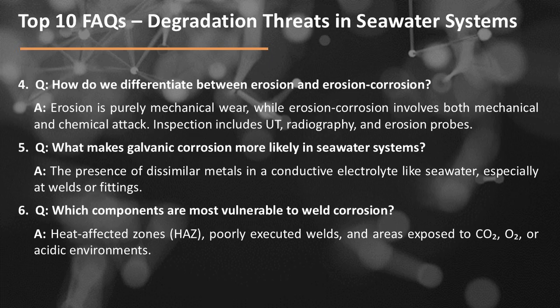Question number 6. Which components are most vulnerable to weld corrosion? Answer: heat-affected zones, HAZ, poorly executed welds, and areas exposed to CO2, O2, or acidic environments.